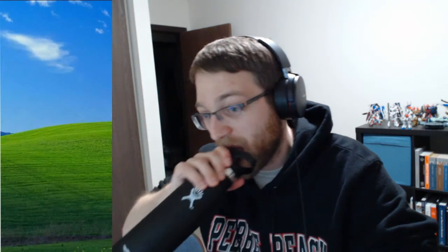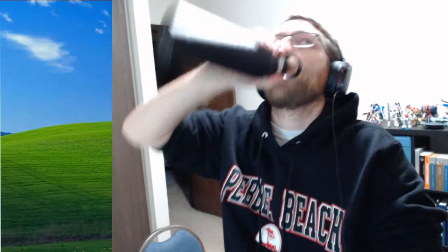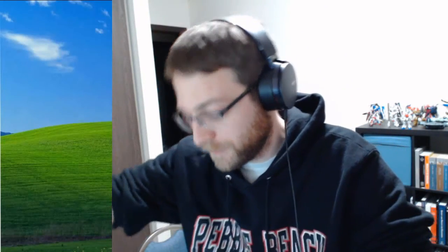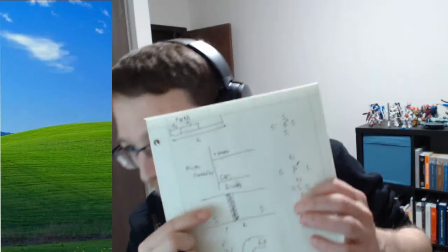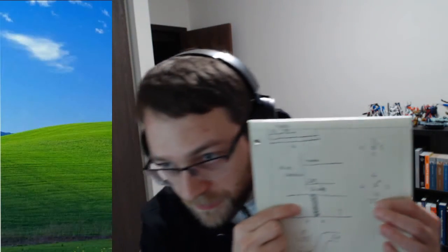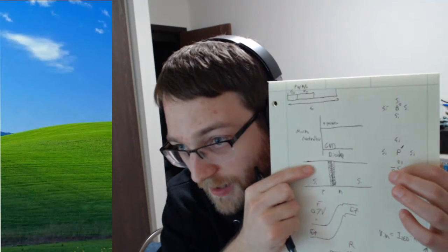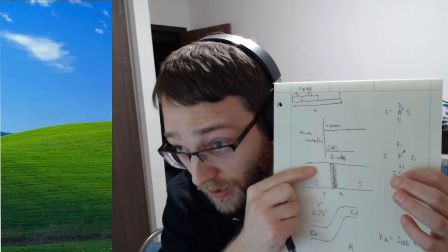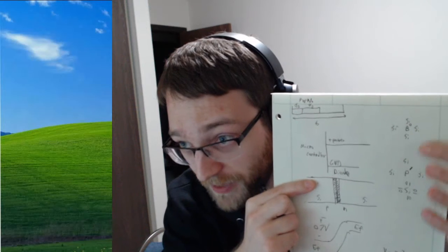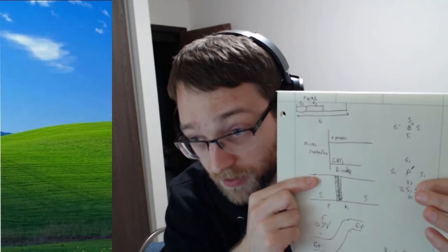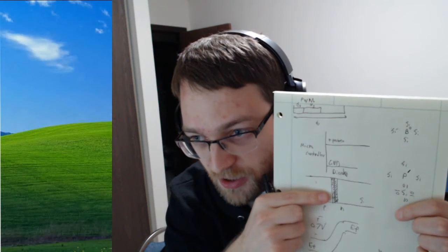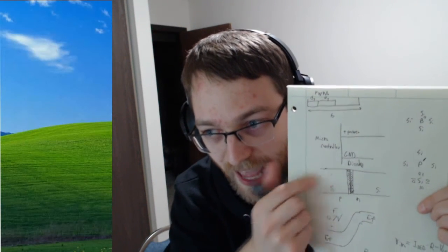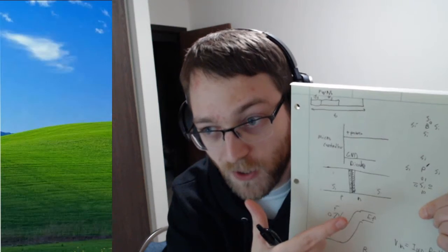This sounds like some of my maths profs' tests that are just awful like that. Especially when we go back to this stuff here, what matters is the concentration of whatever dopant you have in here, the boron or the phosphorus, and depending upon how well it's doped, it changes how wide this middle zone is into each part of the silicon.